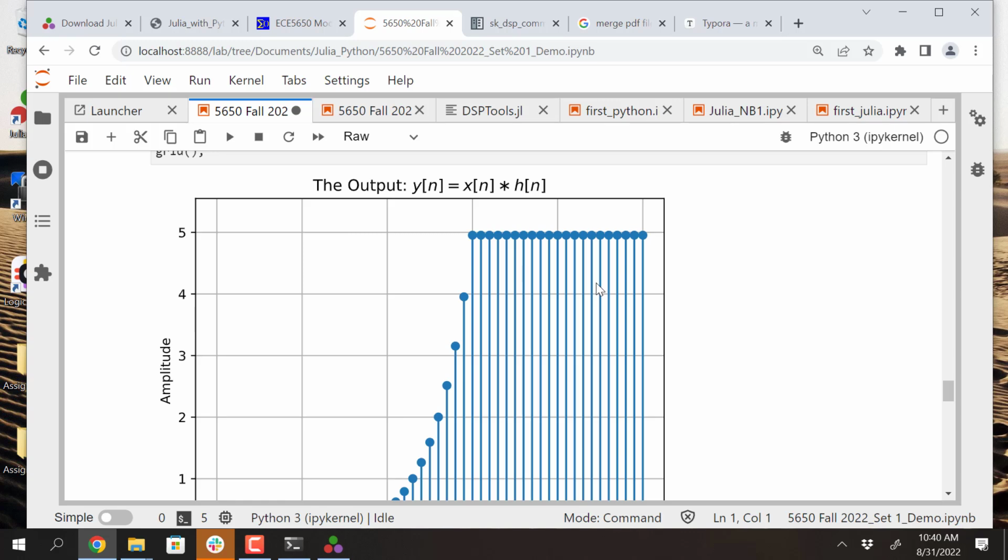And this is a mind-boggling thing, because a system that has an impulse response that runs in the negative direction is not an analog system you can relate to. It's not an RC filter, because that's a causal filter. This is an anti-causal low-pass filter, and you're not used to seeing an output that would behave like that, because you're not used to a system that would be anti-causal. But in DSP, you have this total flexibility to just define something that way.